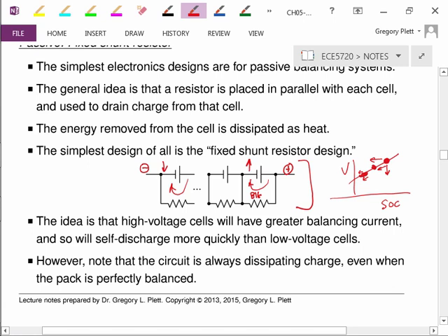Now the balance point here is when the voltage is zero. That's not an especially useful balance point. So we have to take great care, if we're going to use this battery pack, that we're never leaving it unattended for long periods of time, because it could self-discharge through this external resistor down to zero. This design is probably most appropriate for something like an uninterruptible power supply, which is almost always fully charged except when it's needed.